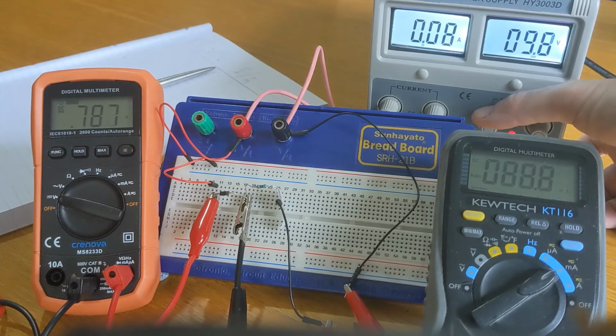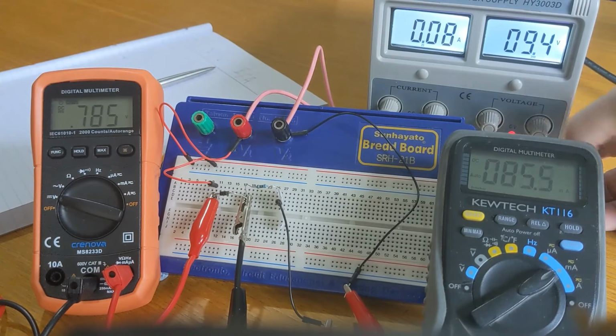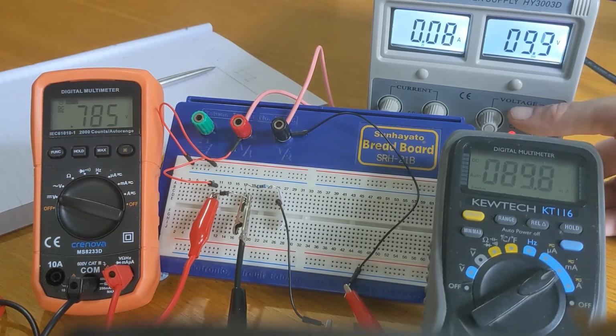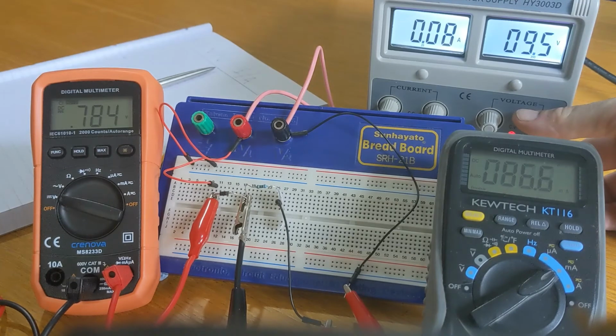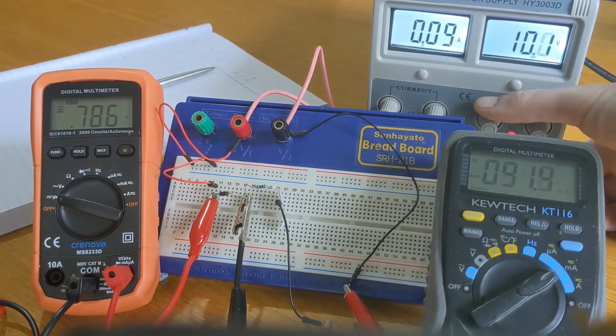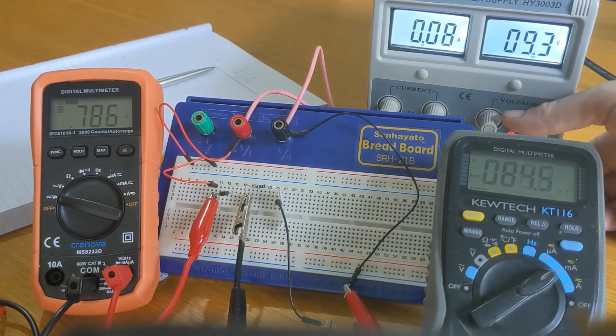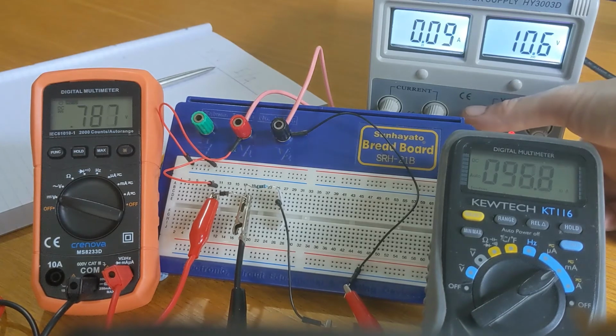So remember that most of that power supply's voltage is now being taken by the resistor rather than the diode, which is increasingly becoming a very good conductor. So a large voltage is beginning to take place across that resistor. So we need to be careful not to go too far now with our measurements.